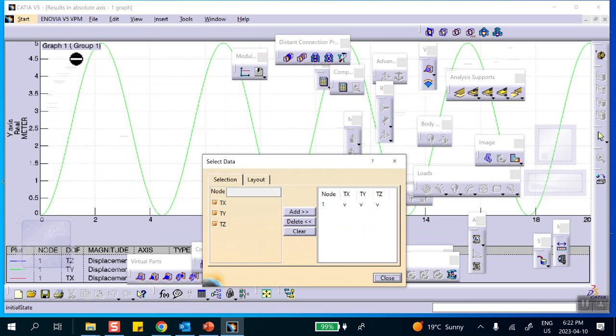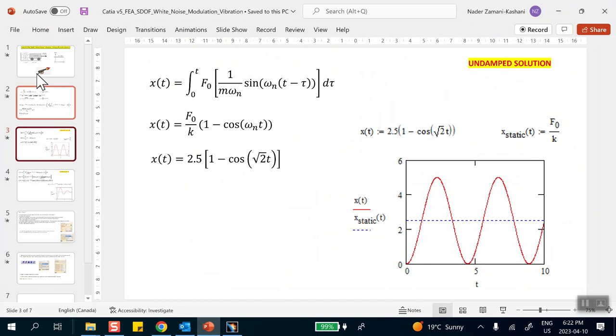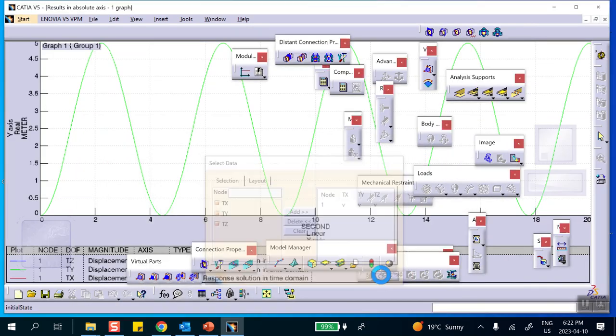You can see that before, the amplitude was decreasing, and it was 1%. By default, it took 1%, and I didn't mind. My situation is not 1%; it's 17%. But what I did, I made that 1% to 0, and now you can see that this is actually that solution. Okay. And by the way, the period, you can see, is about four and a half seconds. Now, if you want to actually change the damping to what it's supposed to be, 17.6, right?